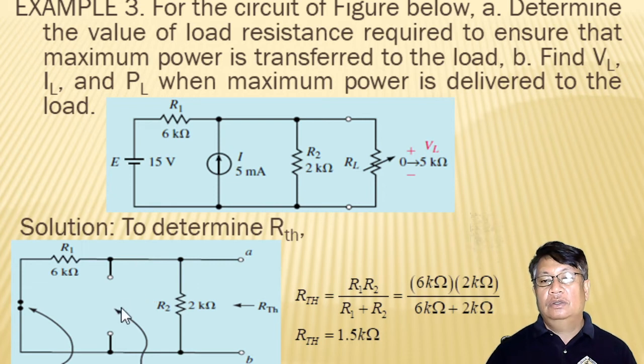So we have this circuit now. Just to investigate, this portion here is short-circuited, and this portion here is open-circuited. So what will happen to our two resistances, R1 and R2? They are now simply connected in parallel. So R sub 1 is in parallel to R sub 2.